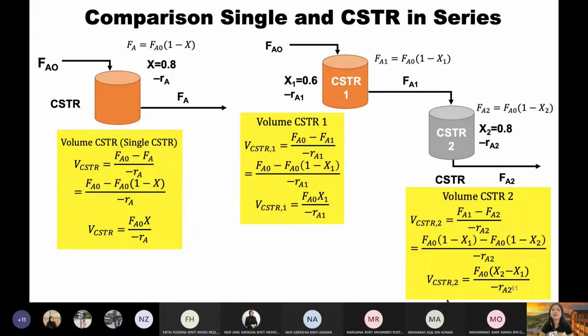So that's how kadang-kadang logic plays a part in engineering. You know logically volume reactor takkan negative. You cannot get a negative reactor volume. So bila kamu kira dapat negatif, kamu dah tahu logically volume reactor can never be negative. So you recheck your calculation. There is a part that definitely that you made a mistake. So this is a way for you to check. Sebab kalau kamu letak X1 tolak X2, confirm jawapan negatif, confirm salah. So kamu switch je lah, letaklah balik X2 minus X1. So most likely, definitely get a positive answer and definitely that's the right answer.